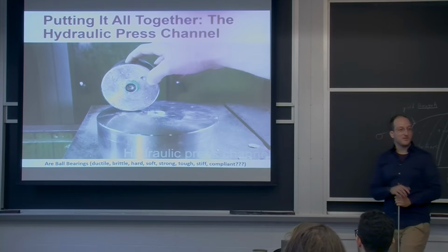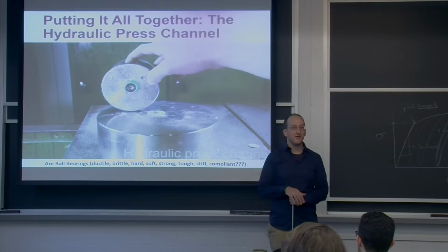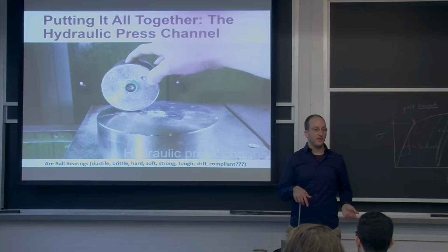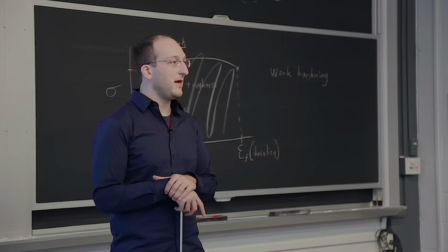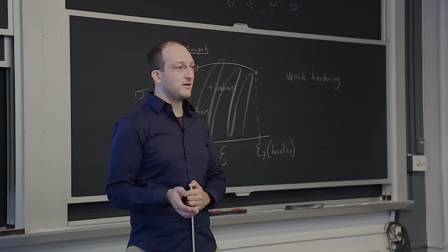Yeah, quite a surprise, right? So in this case, materials like hardened steel aren't necessarily that brittle. In fact, you wouldn't want a ball bearing to be brittle. If you get some small chip in it or a little bit of grit or sand in the bearings, you would shatter the ball bearing and cause instantaneous failure of the rotating component.